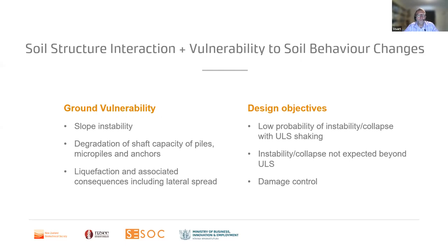So ground can be vulnerable to deformation and reduction in stiffness and strength as a result of earthquake shaking. You know, those sorts of issues associated with slope instability, degradation of shaft capacity of foundations in overload situations, and liquefaction associated consequences of lateral spread.